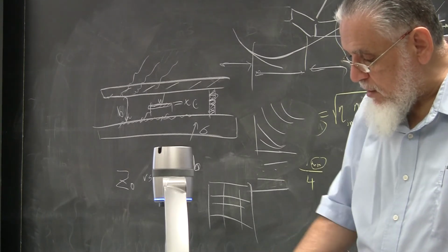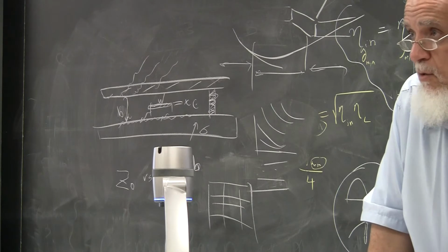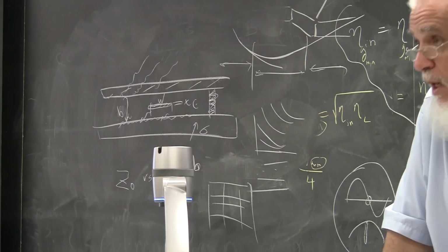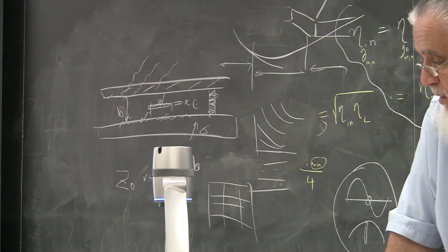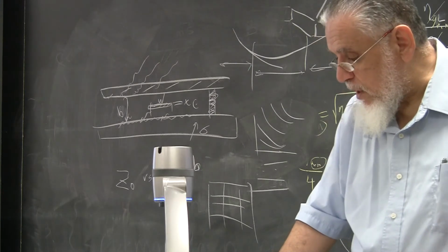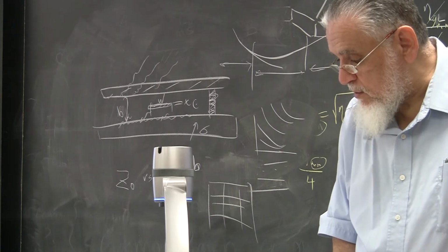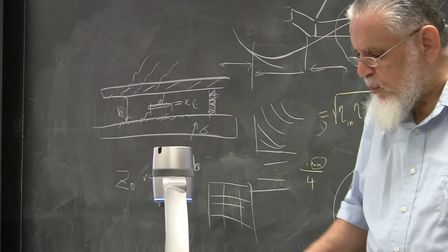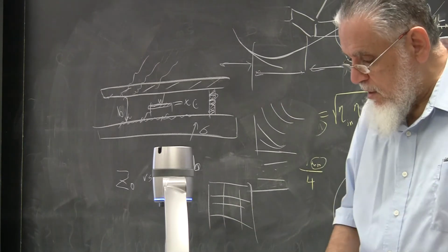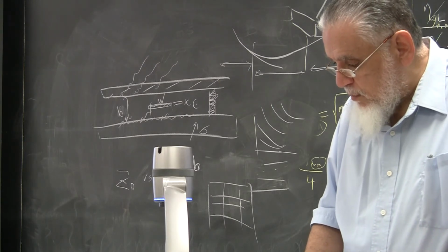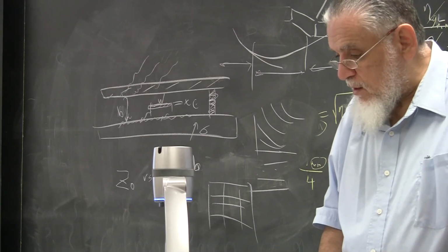You look at alpha sub C here. There are two types of alpha in this case. Two types of attenuation: attenuation because of the conductor, and attenuation because of the dielectric. And both of them have to be accounted for. And as you can see, there is a very complicated expression for alpha C, and there's no way you can think that this is derived somehow. Right? 2.7 times 10 to the minus 3. What's that? Where did this come from? It came from the curve fitting expression, and you have an A and B, and look at the A and B. Again, more complicated expressions.